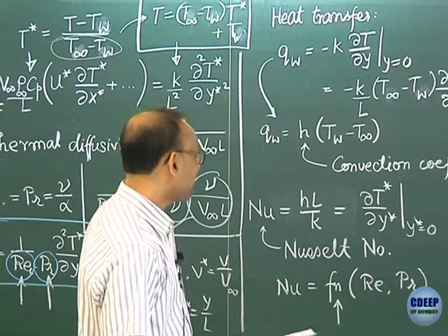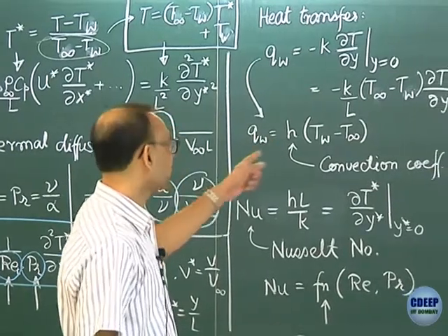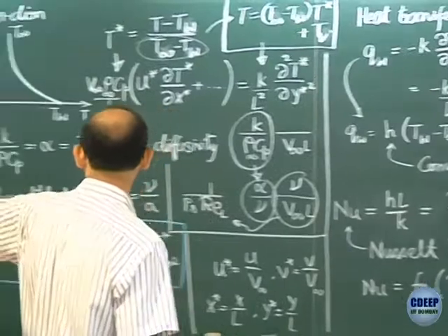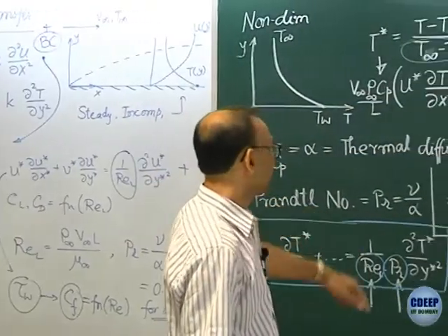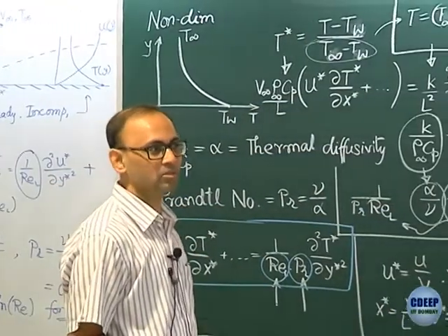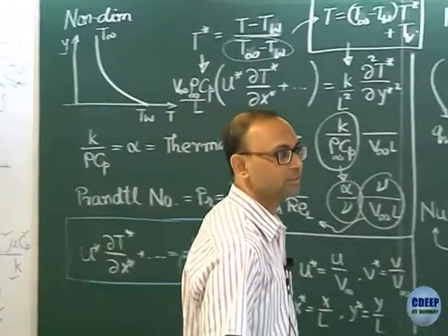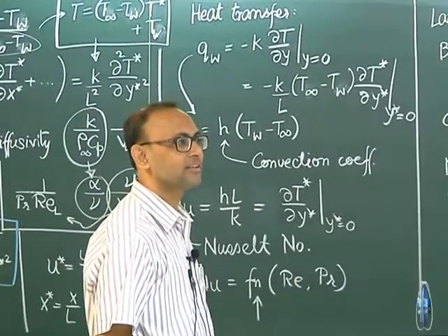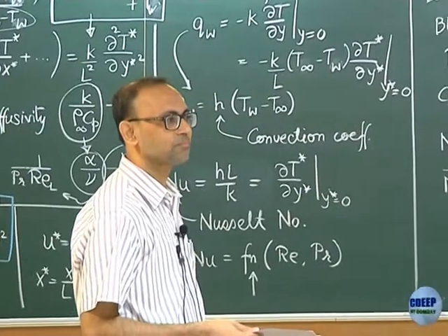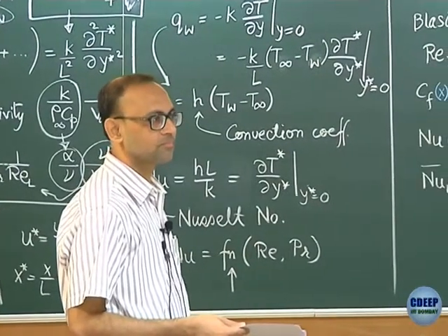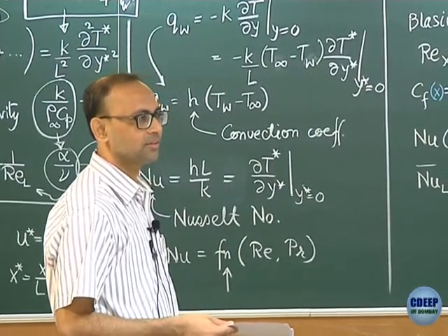And this also happens to be something that actually can be solved from the governing equations, the way we lined up the momentum equation and the temperature equation. Most other situations you cannot really solve. Yes? Can we, there was an approximation of the velocity profile, which was parabolic.